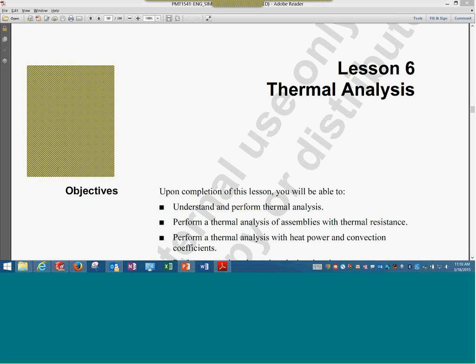The other way around, you want to do further detailed analysis and understand the localized components in more detail. Then you need to do submodeling, wherein you drill down to that particular local component and understand it in more detail. That is what is required as per the necessity. In many cases the stresses are well spread out, not in a localized component, so you may not require it.